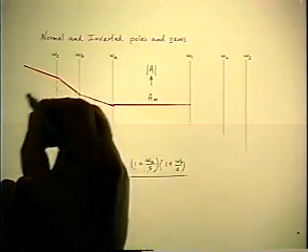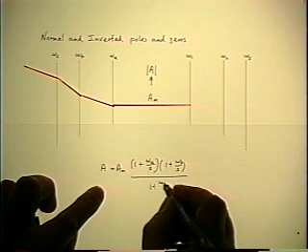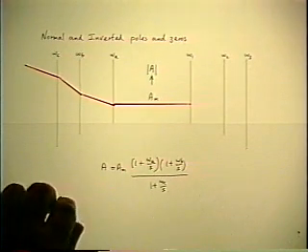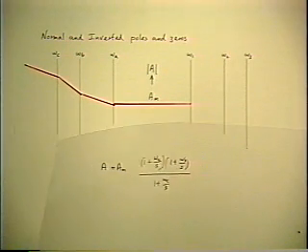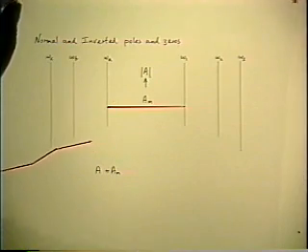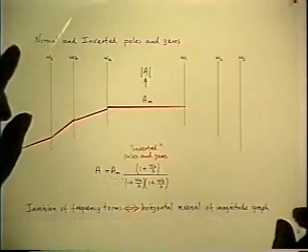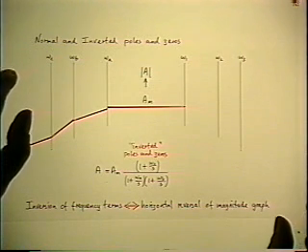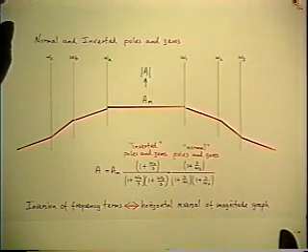And finally, it bends downward, so it's a denominator factor, and you're still going down in frequency, so it's an inverted pole. Okay, now I'll go back to the previous case, which is that, and it has this function. But of course you can have normal and inverted poles at the same time.